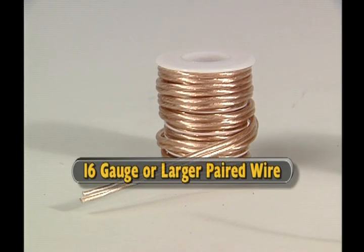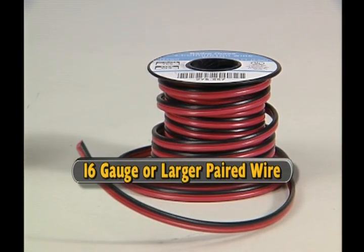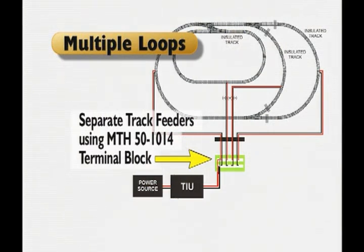For best results with DCS, we recommend using 16-gauge or larger paired wire and home run wiring rather than a common ground wiring setup. This means that separate power feeders should extend out from a central point to the various track sections around your layout.